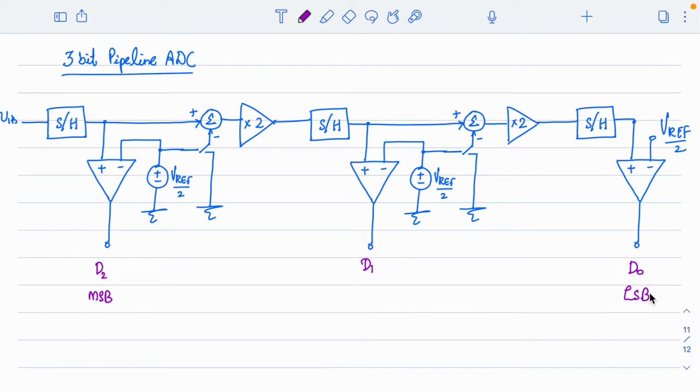All right. Now, what happens is your input signal will be available here, and the input signal will first be given to the sample and hold circuit, and say you are getting some output over here, and let me call this some Vx voltage, which is the output of sample and hold. That sampled input signal is directly given to the plus input of the comparator.